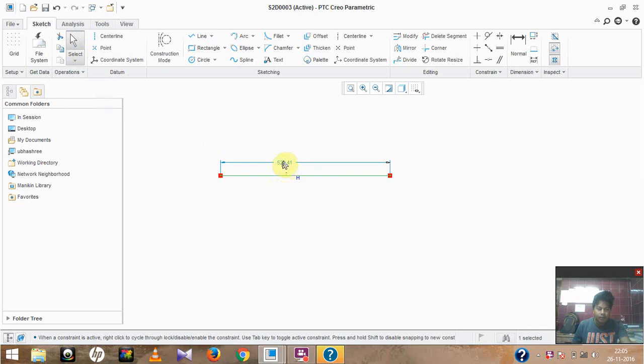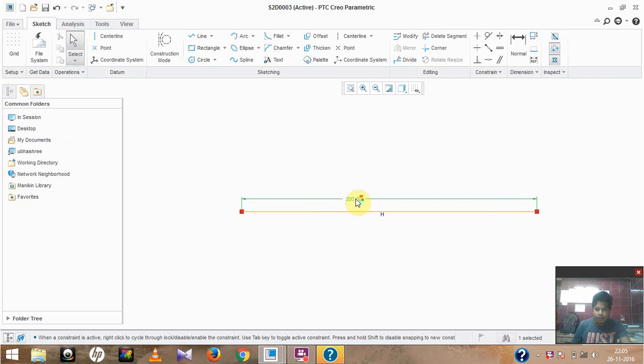You can see it automatically defines the distance between these 2 points. As you can see, the distance is given as 520.40 and so on. So make it 200. Accordingly, it takes whatever magnitude we have given, and it makes the line a magnitude of 200.